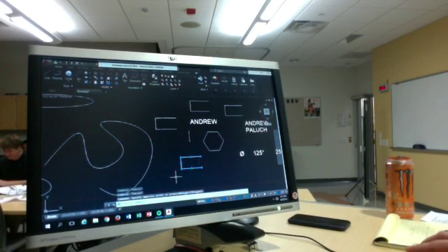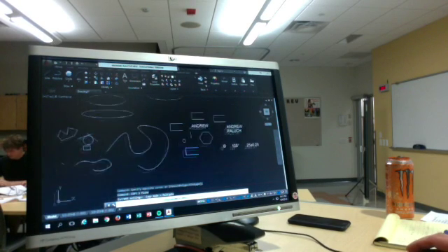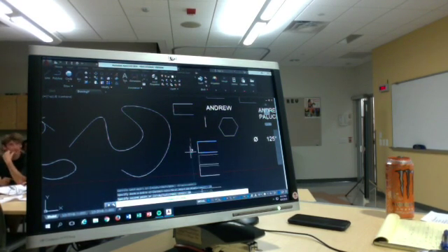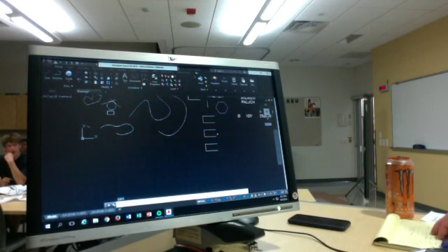What's cool is that copying can actually be directional. I use this a lot at my job instead of offset or what's called an array. So you can copy it this way, 25, 50. So you can do directional copy. We already did offset, right? Yeah, we already did offset.